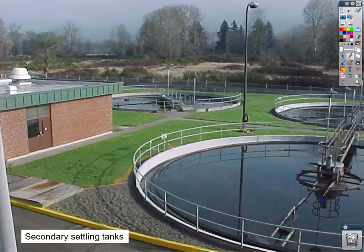The common practice is to pump the water up the middle here, the dirty water, and then it goes out. All right, so it comes up this circular thing and out. And all the while, as it's coming out of this circle, it's moving very slowly. This arm right here swings around very slowly, and it'll skim any greases and oils that got through. So it'll skim that off, and it'll also stir the tank.